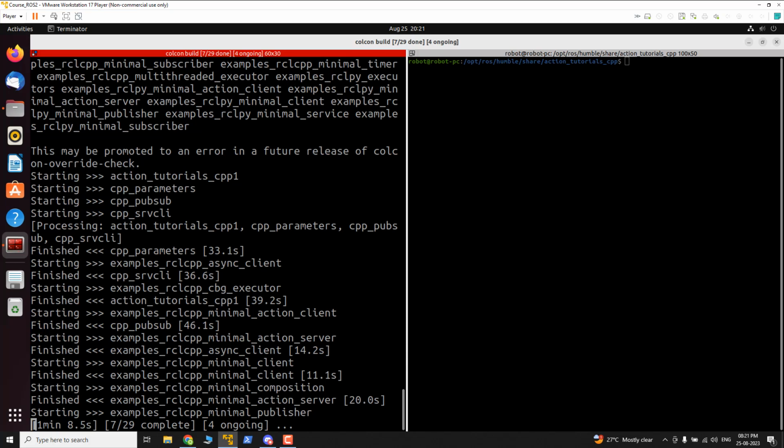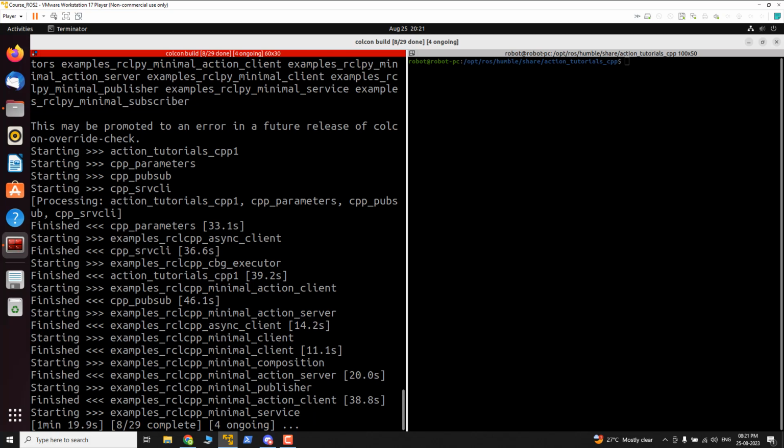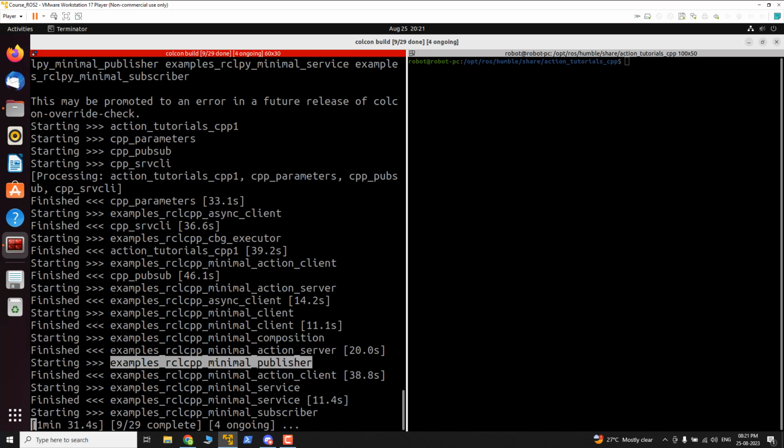If it is a prototype or something that doesn't require much security or new features that ROS 2 gives, then ROS 1 is okay. I'm still working on the implementation; some of my projects are in ROS 1. So it clearly depends on the application and also the client requirement.